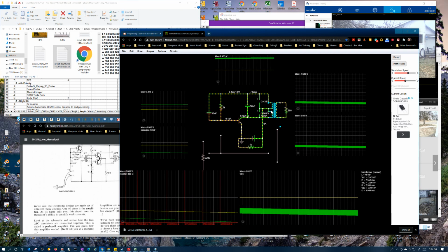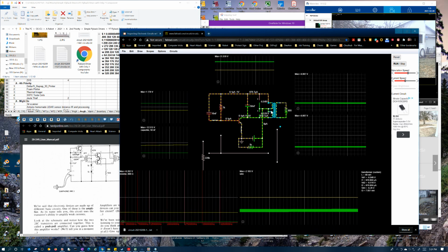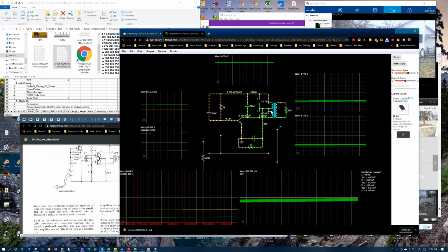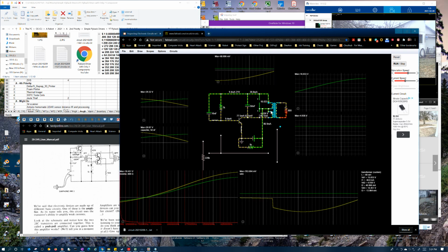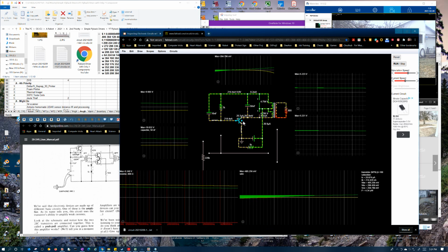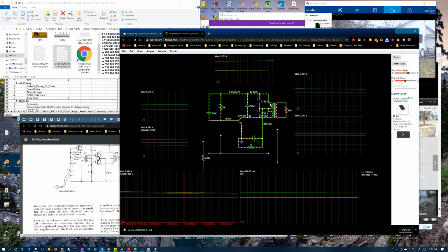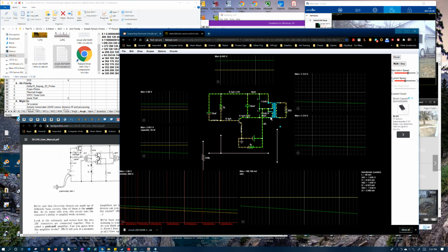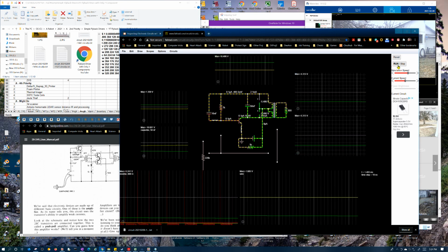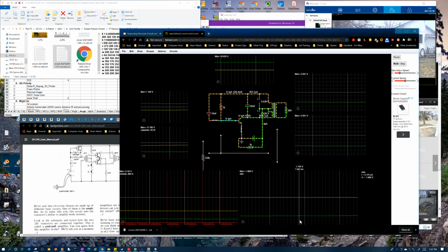I imagine this thing is not very good at handling this, would be my guess. Because that's what I expected: once this transistor is off, this field should collapse, and as it does, it reverses the voltage across these coils, thus sending this voltage negative, which in fact is what happened.